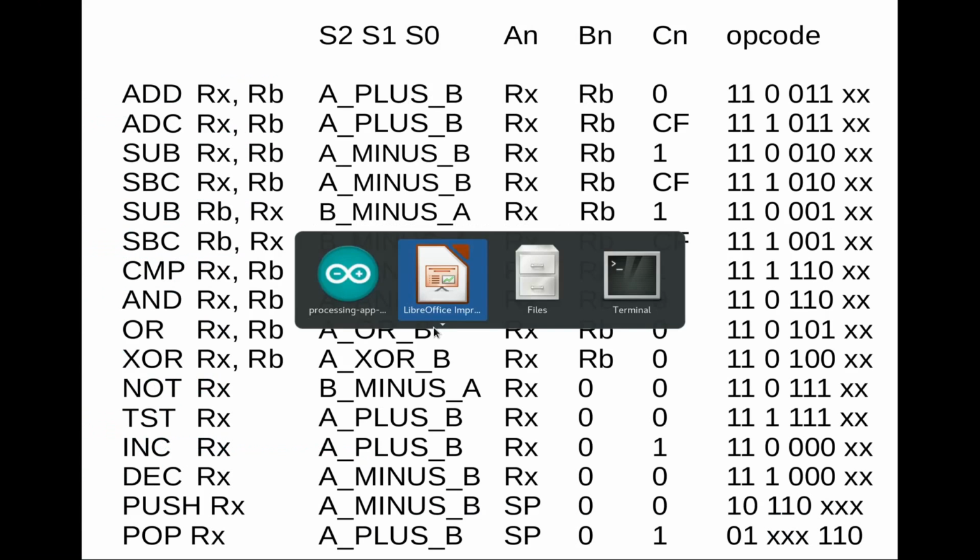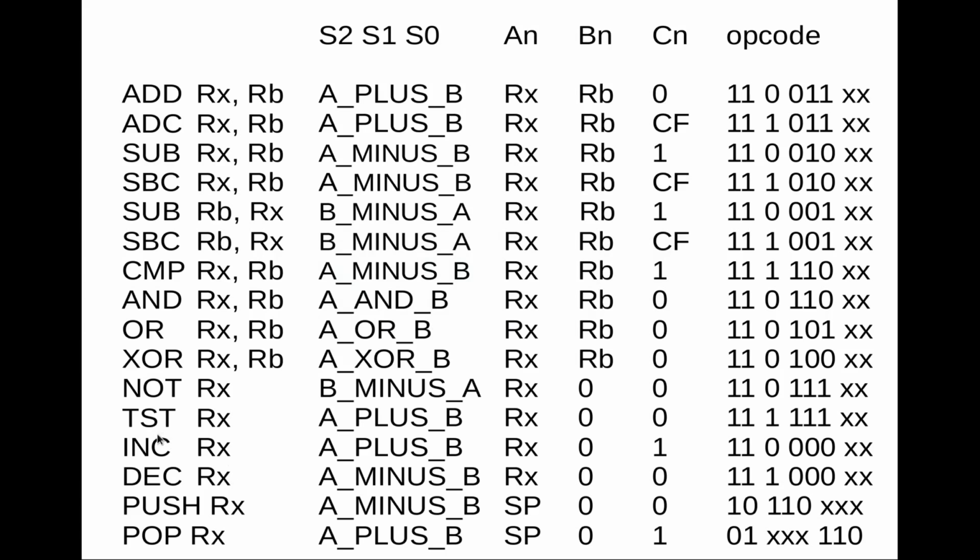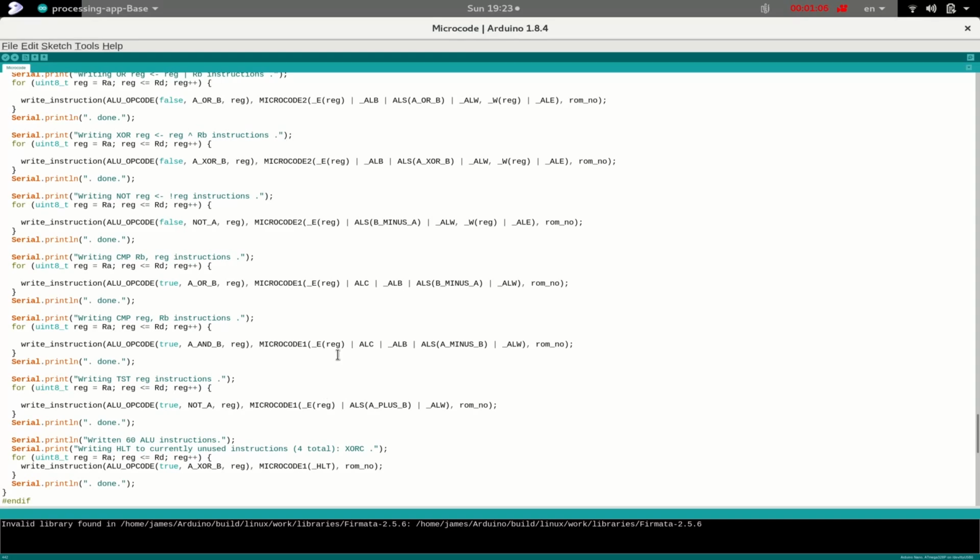And so once again, we've determined what that operation should be. For the test instruction, that's this plus with a 0, which will simply set the flags based on the value in that register. And the compare instruction should perform subtraction and then set the flags according to the result of that subtraction. And so both of these instructions, as it turns out, only need one extra word of microcode, apart from the fetch cycle.